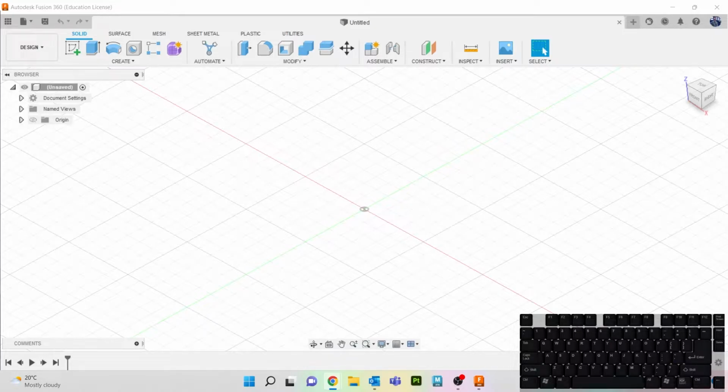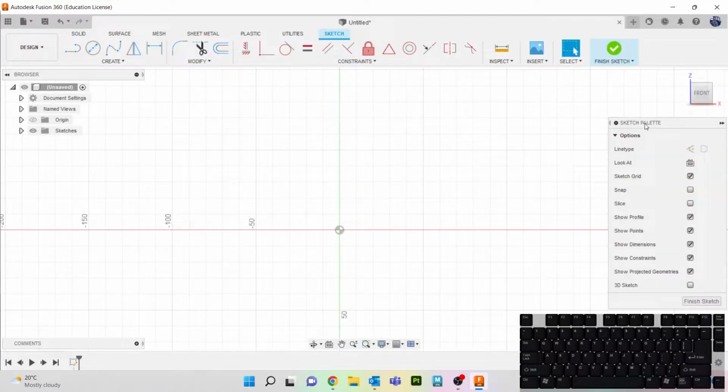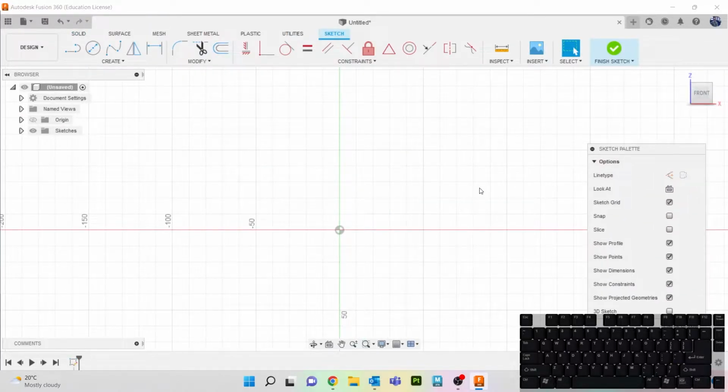Okay, so what we're going to do to begin with is start a sketch, and I'm going to go on this plane here. Now I'll talk through it. I'll go quiet because I'm trying to look at the measurements on the drawing as well, so apologies if I suddenly sound like I've disappeared. When you're going to do a sketch, it's always worth making sure you do it at the origin, because if we're going to mirror things, it just makes things a lot easier.